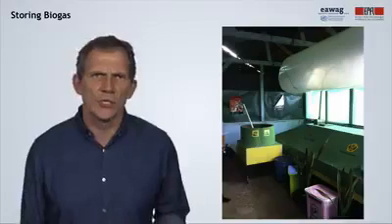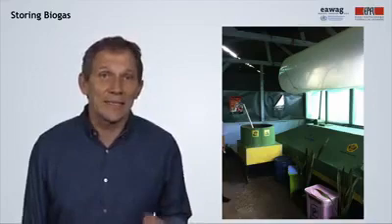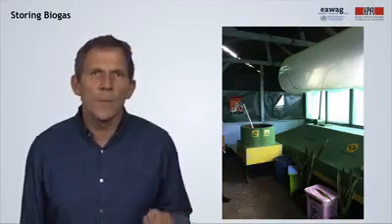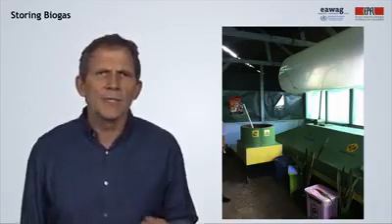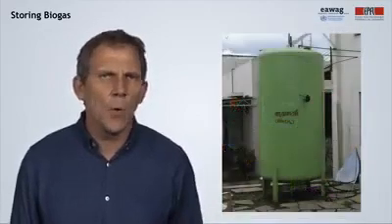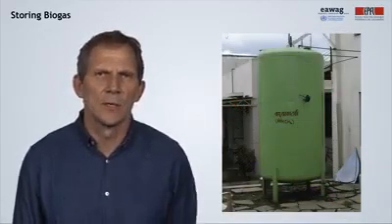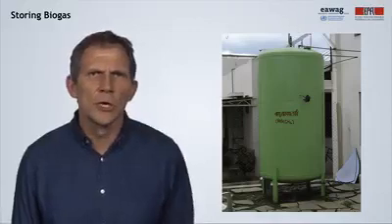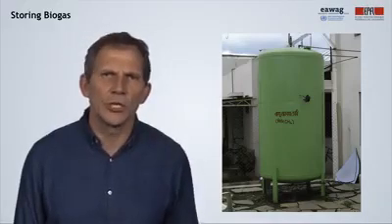The biogas produced in the reactor will vary during the day according to feeding patterns and also ambient temperature changes. Biogas production also continues during nighttime, when less gas is used, and therefore there are periods when the gas has to be stored. This can either be in the digester itself, as in the top part of the fixed dome digesters, as we had seen before, or in bags or balloons, like in this unit in Indonesia. Gas can also be stored with medium or high pressure in gas tanks. This can be done with compressors, but of course, this requires energy.